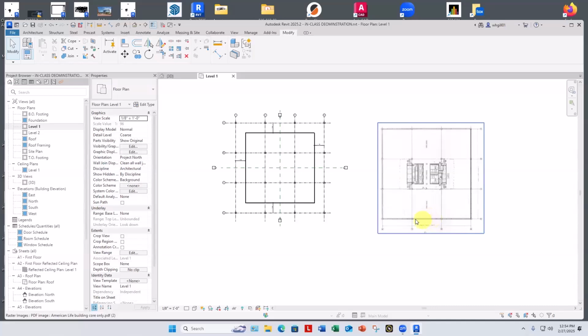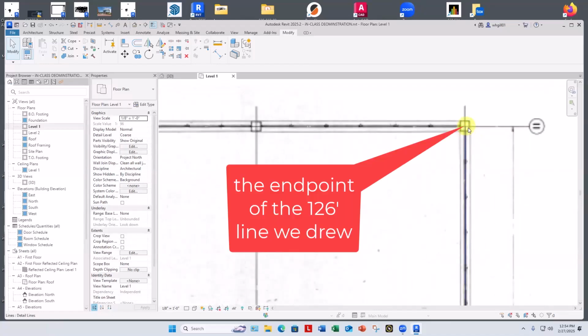And the reason we're not seeing the doors here, this is like a second or third floor plan. It's not the ground floor plan. What it does share with the ground floor plans are the columns and these center cores. Okay, now, when we dropped that AutoCAD drawing in, it was just origin to origin. It knew where it was supposed to go. We don't have an origin for this guy. This is just pixels. What we do now have, however, is this point right here, which we can use to move from right here over to the corresponding point in the plan.